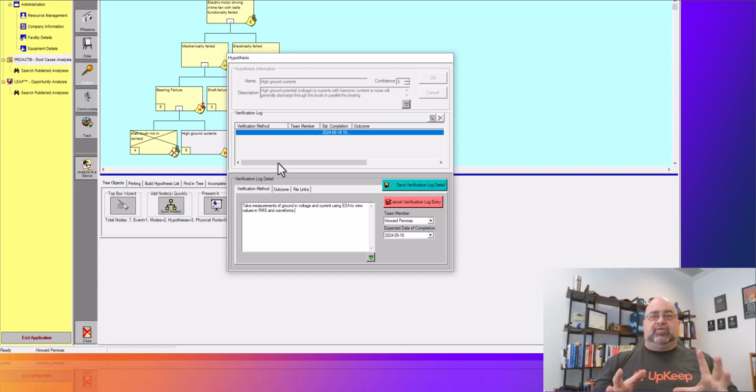I have seen cases where people put ceramic on the inner race of the bearing. Well, that's because the tooling from the bearing manufacturer is less expensive. They can use that across many things. So they'll put a coating on the inner race, which keeps it cheaper, and then when it doesn't expand and contract, it will start eating away at the material on the shaft. Or worse, the shaft will expand and fracture that ceramic, meaning that I have a fine point for discharge, which changes everything and makes it much worse.